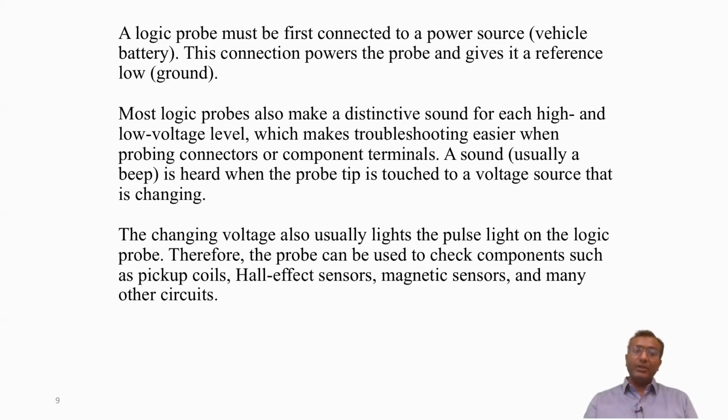The first caution is we have to be cautious with certain types of test lights and continuity testers around sensitive electronics. Testing a modern car's computer circuit with a standard continuity tester could lead to costly damage due to the tester's internal voltage. An LED test light or a logic probe is safe for this application.